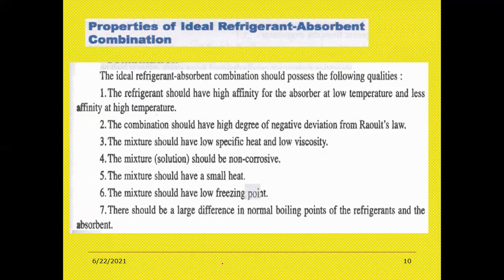So what is the first point you have to keep in consideration? The refrigerant, whether ammonia or whatever you are using for this vapor absorption, should have less affinity at high temperature and high affinity at low temperature. Simple. Less affinity at high temperature, high affinity at low temperature.